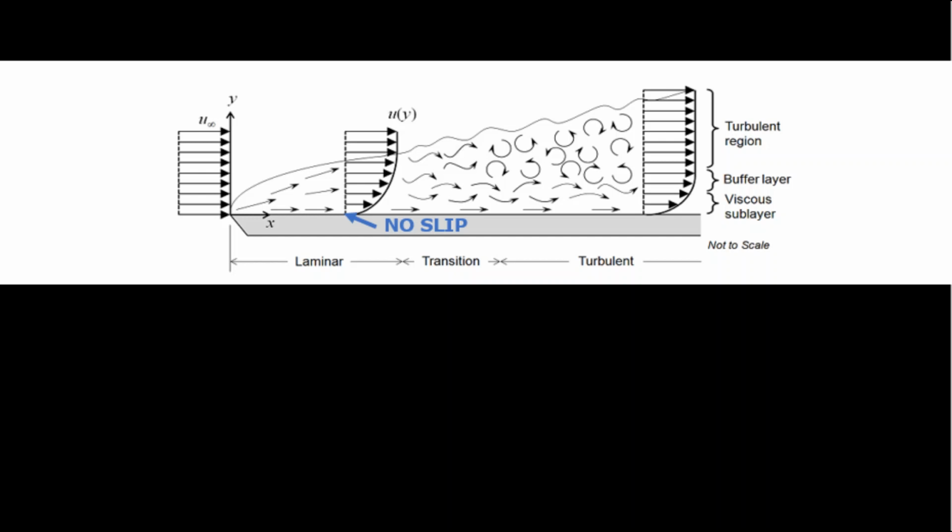And the concept of boundary layers is not only important in fluid mechanics, but also in the theory of heat and mass transfer. Why is that? Because we're going to find that we have diffusion of heat and mass across boundary layers, and this diffusion process across the boundary layer will often control the rate of heat and mass transfer operations.